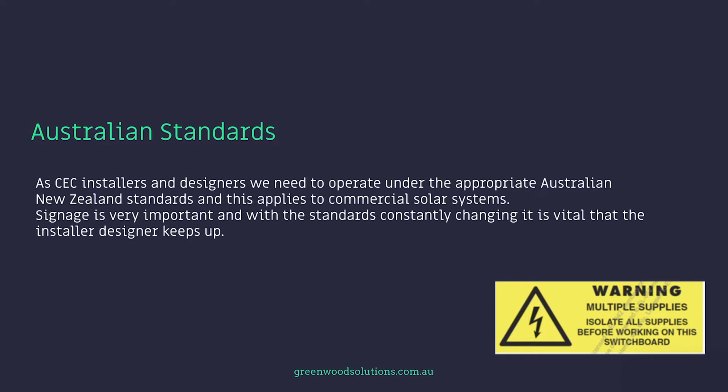As CEC installers and designers, we need to operate under the appropriate Australian and New Zealand standards, and this applies to commercial solar systems. Signage is very important, and with the standards constantly changing, it is vital that the installer designer keeps up. Remember, signage serves multiple purposes. It's there to inform emergency workers of what's on site and what the electrical dangers are, and also to inform anyone involved in the system or who may be accessing that system. What are the components? What are the voltages? What are the currents? Where are they located? What are the specific details of the equipment involved?